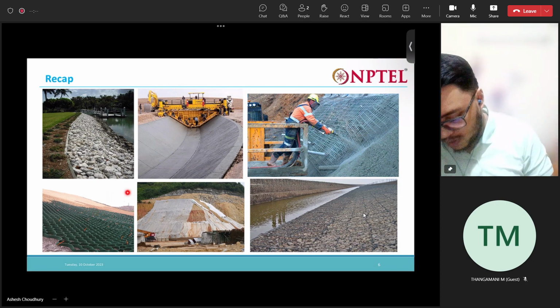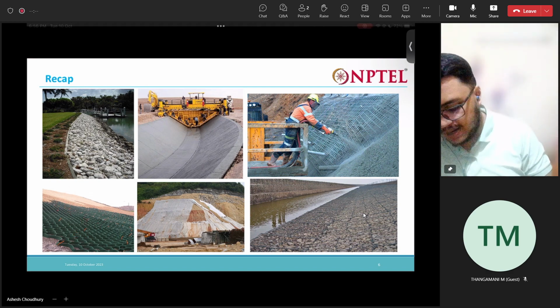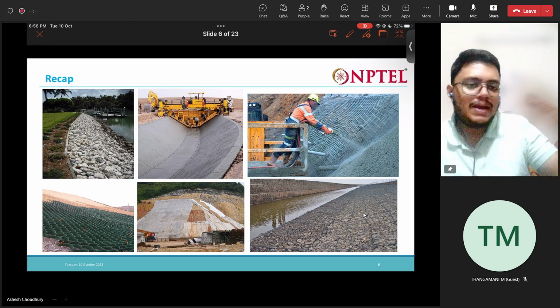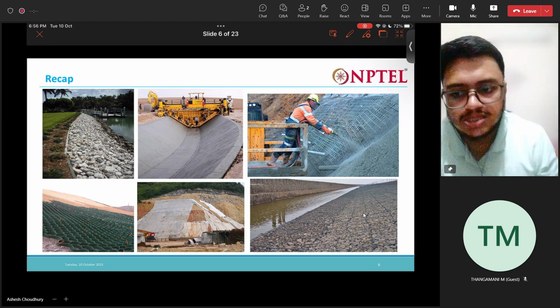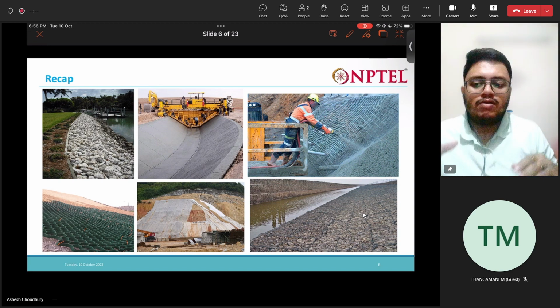So we have a bottom soil which needs to be protected. What we do is place geocell over it, and then we fill that geocell with more soil. Over that soil, we can plant grass or vegetation. So the geocell here will serve two purposes.